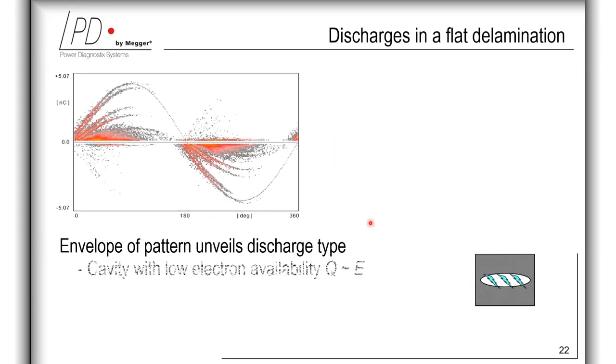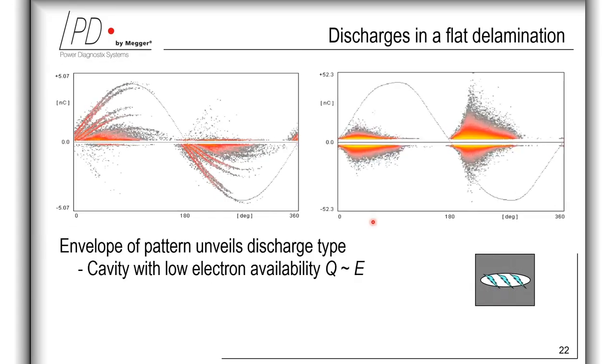So as found with the void discharge process already, the time lag to get a starting electron results in a correlation with the local electric field. Also, based on the found linear relation between the electric field and the radius of the resulting surface discharge, the area covered by this discharge is correlated to the square of the electric field.